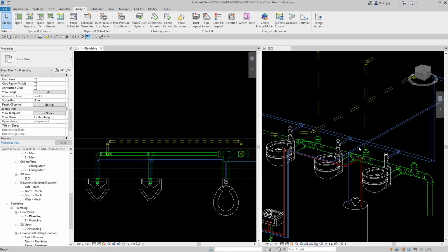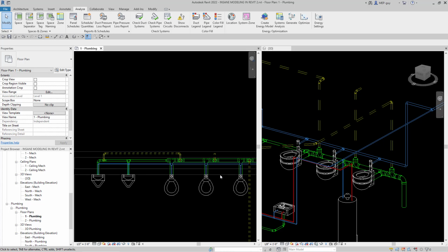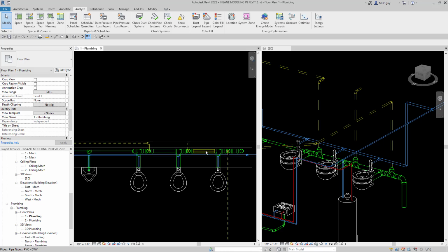Now, in a normal situation, we're probably going to want to use an actual wall carrier. And the wall carrier is going to have a vent connection as well as a sanitary connection to make all these connections work. But I actually like just using piping for this because it's a little cleaner. But you can definitely use a wall carrier if you guys want to get fancy.